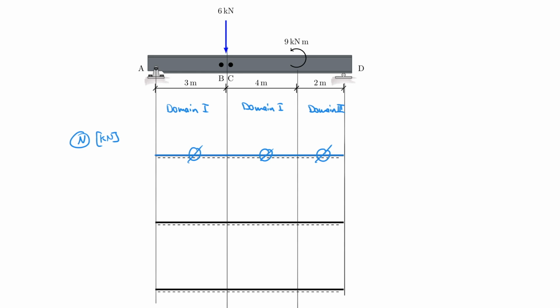That will become more important in one of our next lectures. But now I want to move on to the shear force diagram. And for my shear force diagram, the first value that I calculated at B was equal to positive 5, if I remember this correct. So let's say this here was equal to positive 5. And then at C, I had a value of minus 1, if I'm not mistaken.